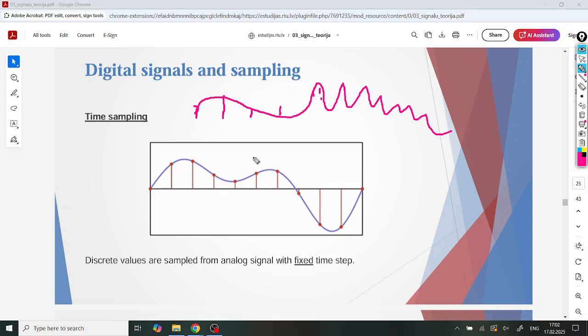Mainly, the main problem is that your receiving device doesn't necessarily know when it has to take a large step and when it has to take a small step. That's not exactly clear, at least not obviously clear. So because of that, in practice, we usually prefer just to go with a smaller step for the entire signal, just to know that your next sample is supposed to arrive at a guaranteed time, which you are expecting, and basically not to deal with this uncertainty, like now my period is higher or smaller?